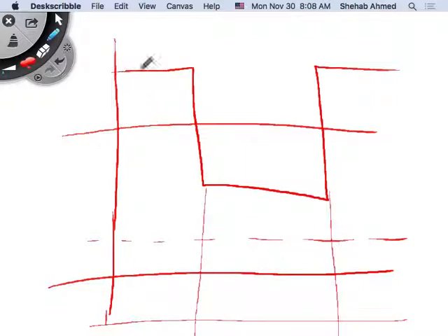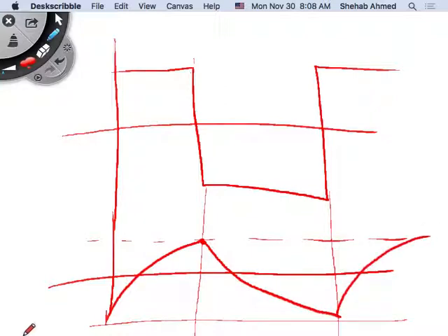Again, this is a fixed value, it's a DC voltage. If it's a pure inductance, the current will look like a ramp. It's not a pure inductance, there's a resistance as well, so it's an exponential waveform. The solution is natural response plus forced response, and it's an exponential. So the peak value of the ramp would have been here at the end of the positive voltage applied across the RL load. So the same thing will happen for the exponential current. Exponential current will look like this, like this, like this, etc.